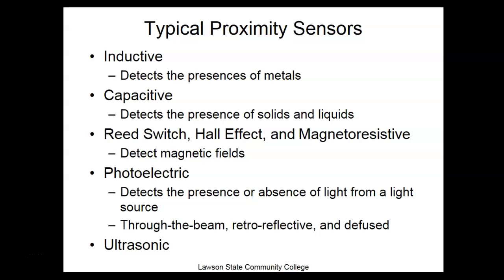But if a car wasn't behind me, then I'd kick my kickstand down and I'd walk over and press the pedestrian walk thing to switch that. So there's a sensitivity adjust on a lot of these sensors. You might want it not to see copper, but you want it to see steel. Most of these sensors, you actually have what we call a sensitivity or a threshold adjust.